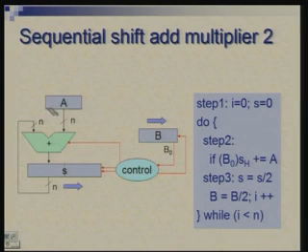So, A is now n bit register, A does not shift at all. The value A gets added to left half of S, and after addition you can shift S to right. So, I have introduced another step here, that after this addition S becomes S by 2. So, which means you are shifting it right, and rest of it is same. Okay. B has been shifting right, the counter increments. So, the crucial change is here that addition is only to the left half of S and S shifts right.